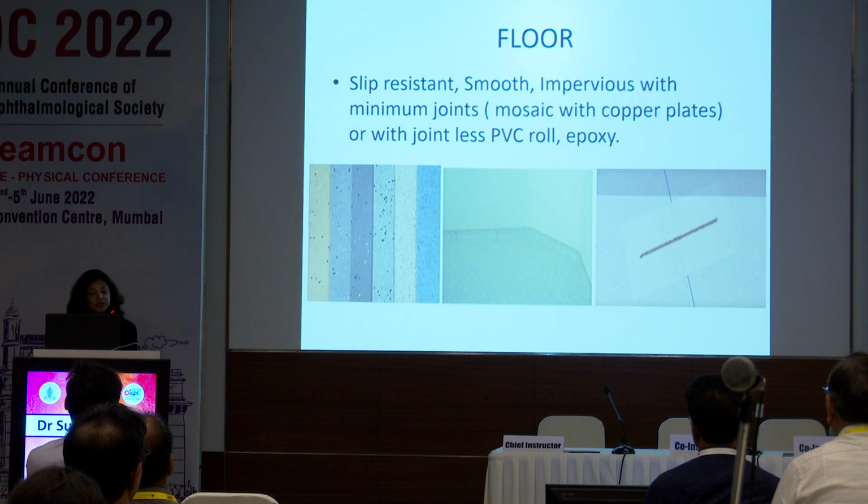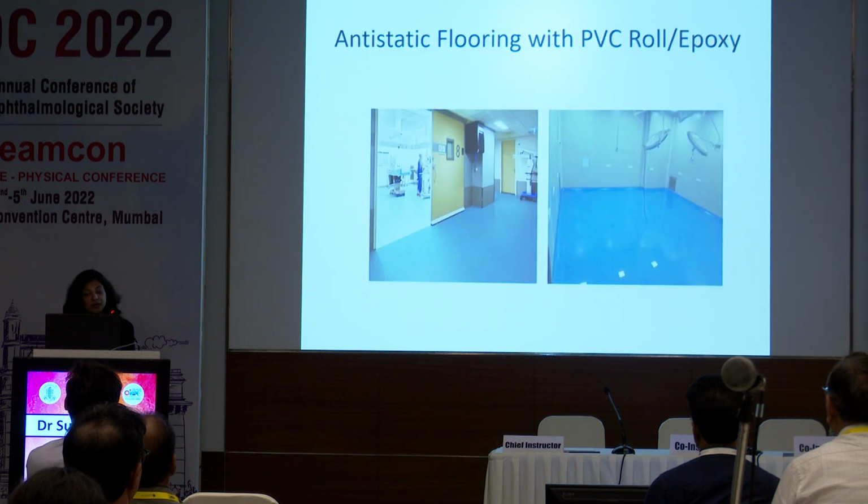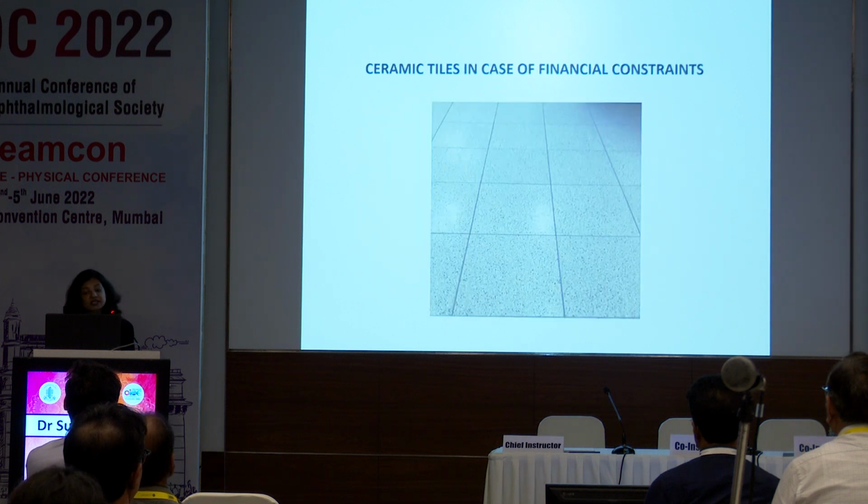Floor should be slip resistant, smooth, shiny, and impervious with minimum joints. Flooring should be either inset mosaic with copper strips to carry away any static electricity produced, or it can be made anti-static by using PVC roll or epoxy. Ceramic tiles can be used if there is a cost issue.